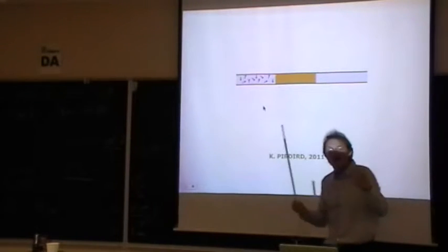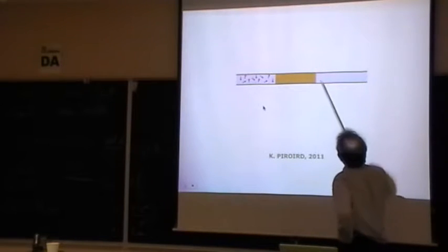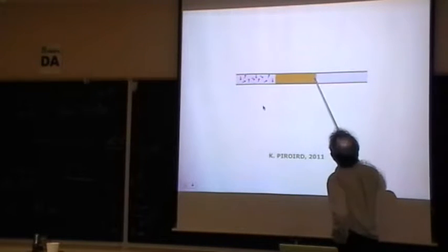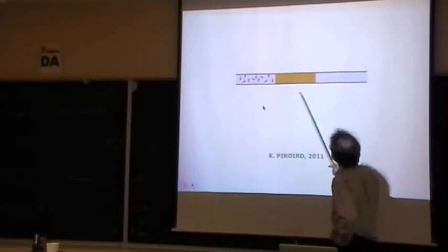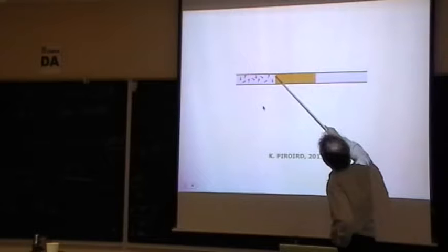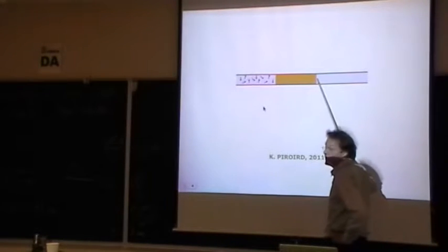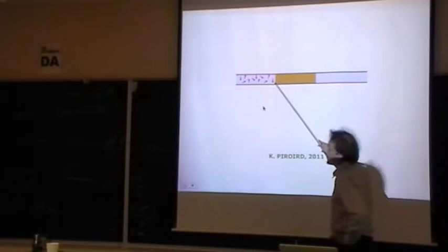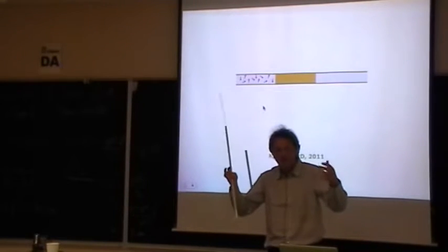And so this should be more or less equivalent to the previous situation, because in this case, the surface tension of the water-oil interface should be affected by the presence of surfactants. Okay? And so I expect in this situation that surfactant adsorbs on this surface, and so there is a difference of surface tension. Here, I did not represent the menisci, but they should be of the same curvature, because it's inside the tube, inside the pore.